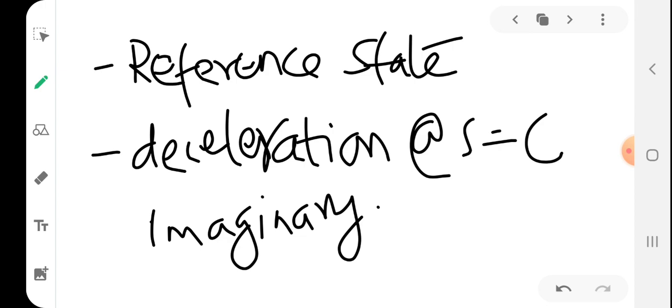Actually in the flow path the fluid is not going to be decelerated to velocity 0, but for the sake of study, we are imagining if we decelerate the flow at a particular section to 0, what will be the condition of the fluid, what will be the properties corresponding to that particular stagnation condition. That is just for the sake of study. So we are defining such a reference state. It is not actually taking place.